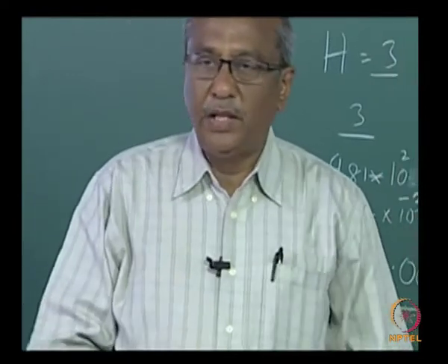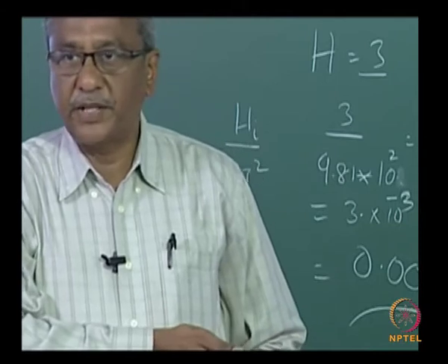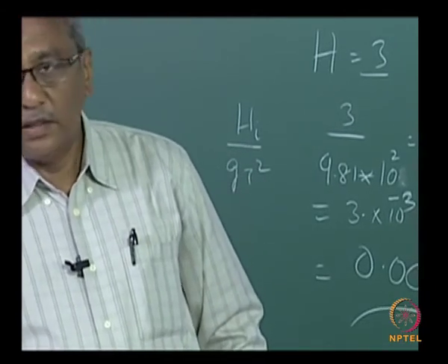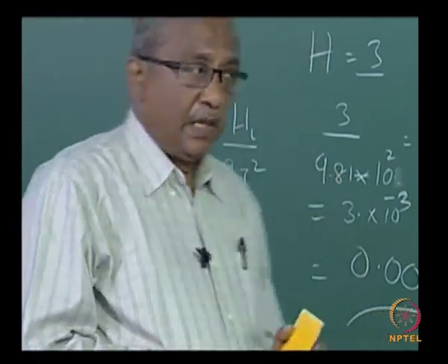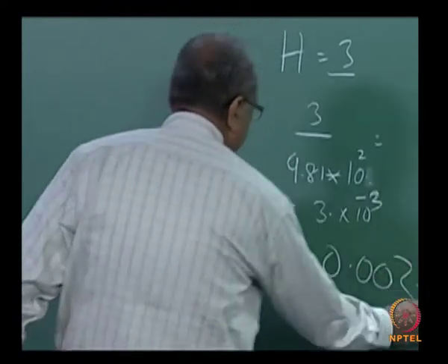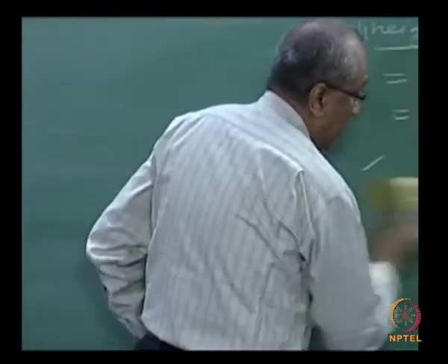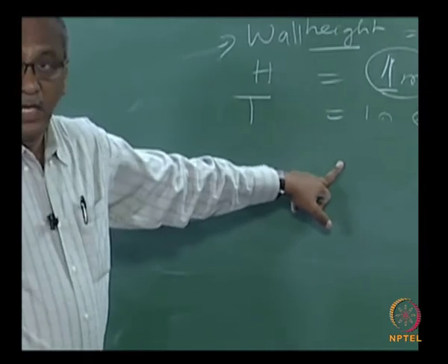Similarly, on one side of the wall you can have soil, so you need to consider the soil pressure; on the other side you might have breaking or non-breaking wave pressures. All these combinations are given. This is a problem which frequently needs to be handled, and that is the reason we have spent slightly more time on it.